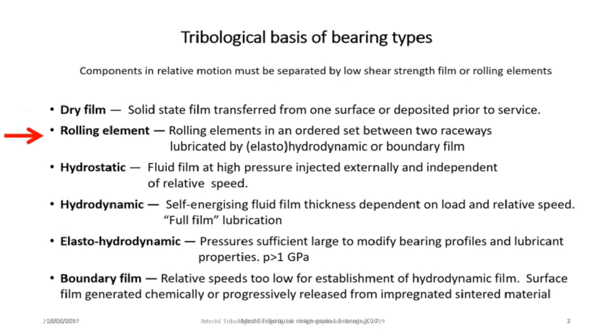Interposing rolling elements between the shaft and the housing gives rise to rolling element bearings. Although now there is no gross sliding between the balls or rollers and the races, these must be lubricated because of the very high local pressures, typically of the order of gigapascals.